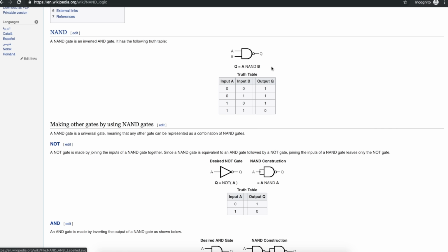So because of the way a NAND works, let's say we keep one input always low, right here. Well, no matter what we do on the other input, high or low, the output is going to be stuck high, so that's not what we want. But if we take one input and tie it high, then the output will change as the input changes, although it'll be the opposite because it is an inverting gate. We can use this functionality to gate one signal with another.